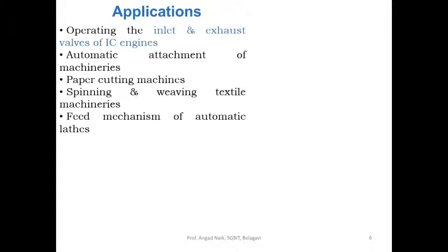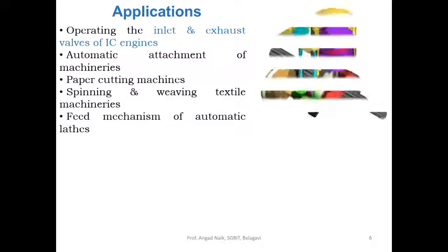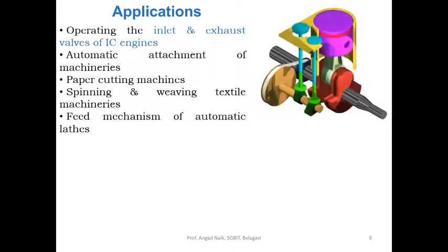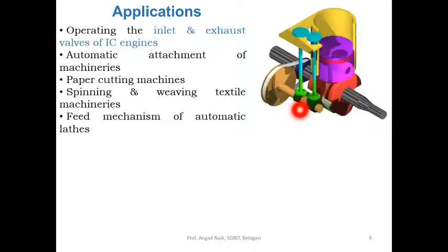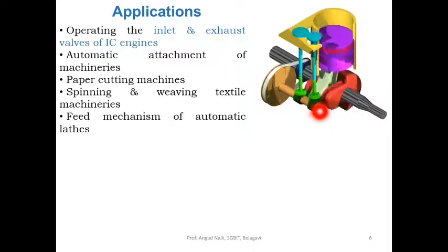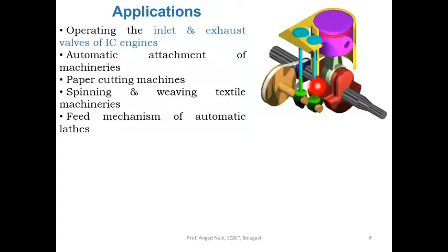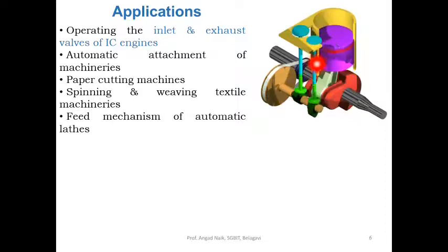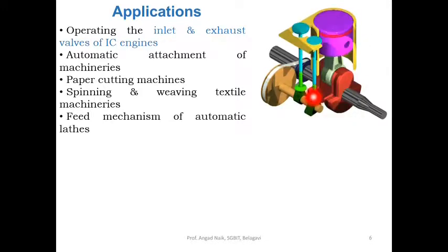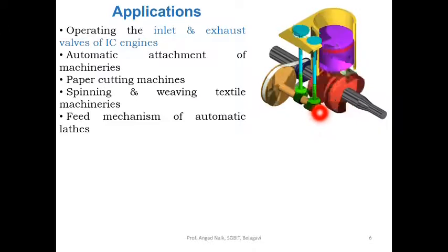Let's see the application of cams. Operating the inlet and exhaust valves of IC engine. So we will understand this with the animation. At the bottom you can find there are cams. These are the cams which are connected to the follower. The followers are connected to the poppet valves, and the opening and closing of the valve is controlled by the profile of the cam.